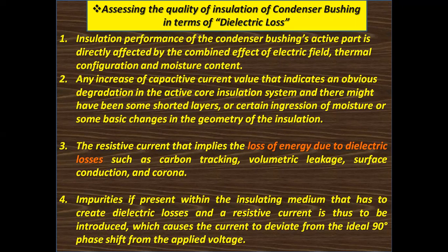Number two, any increase of capacitive current value indicates an obvious degradation in the active core insulation system. There might have been some shorted layers, or certain ingression of moisture, or some basic changes in the geometry of the insulation system of the bushing.